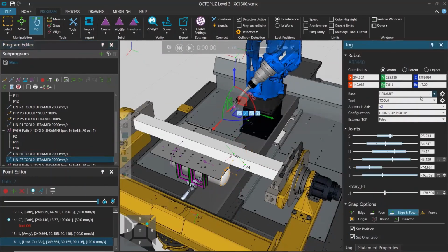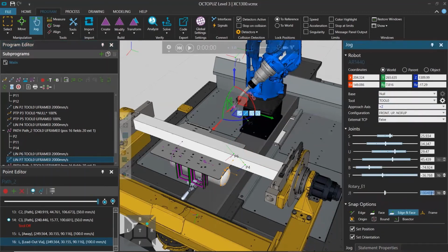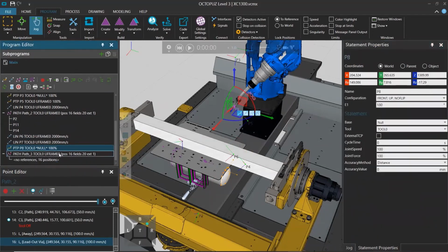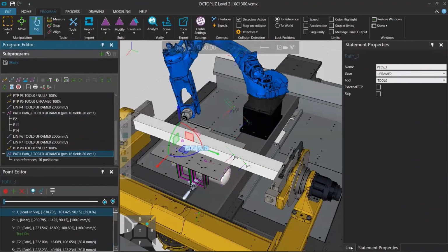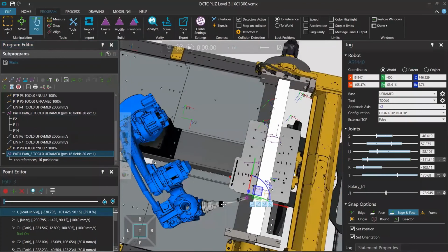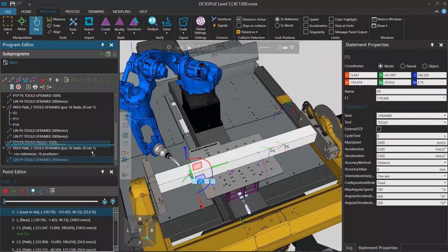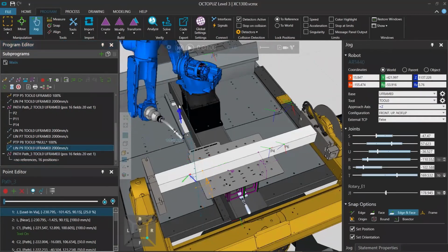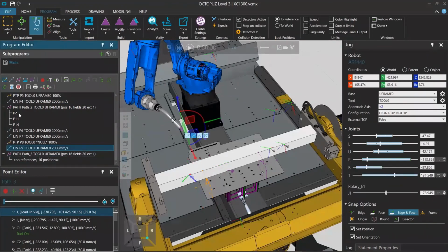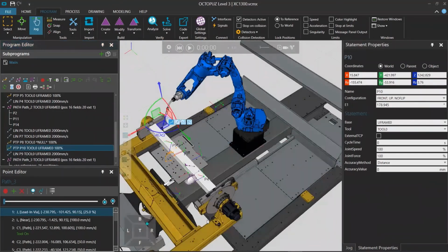And then let's unwind this headstock, tailstock axis to get it ready for the next path that's coming up, that third path. So I'll put in that 180 and unwind it with an air move there. And we'll create some moves leading into our third and final path over on this side. So for starters, just a simple linear motion here for the beginning of that path. And before that linear motion, actually, I'm going to also create a point-to-point motion up above over here, like that. Perfect.